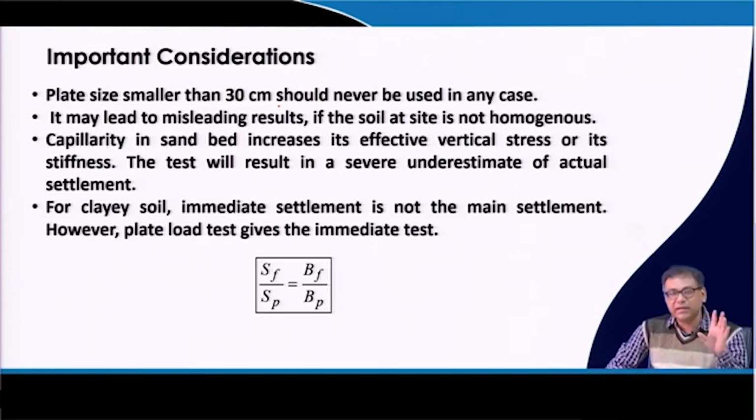So, that means this is very suitable for homogeneous soil. If it is a layered soil, then you have to use this data very cautiously when you are designing the real foundation. And obviously, for clay soil, the immediate settlement is not the main settlement. However, plate load test is an immediate test, so that means a short term test. Again, to use the data for clay soil, you have to be very cautious.